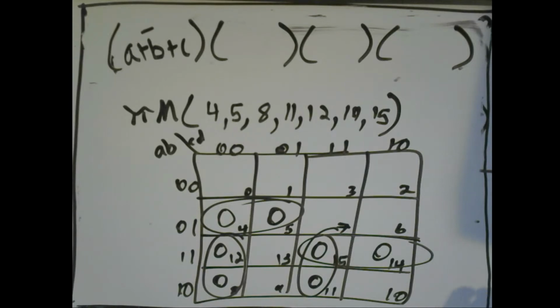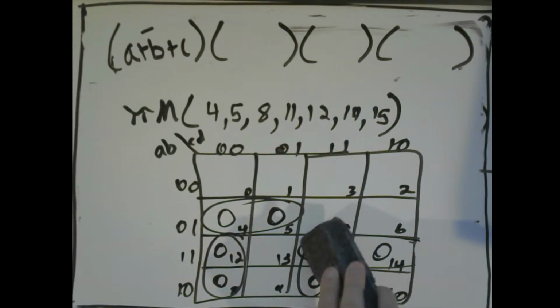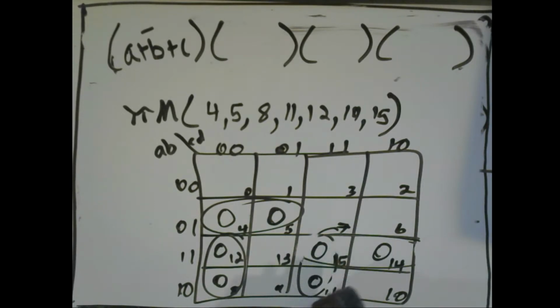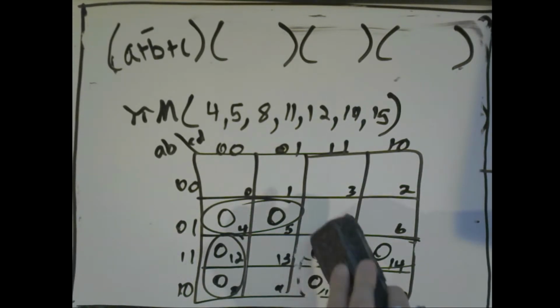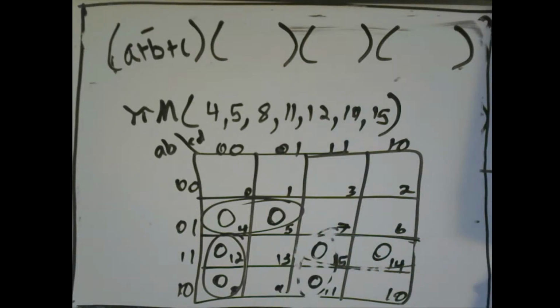And so Joshua was saying that's a good point. What would it matter if the prime implicants are different but still cover the same squares? No, there are different right answers, right? Because I'm trying to cover the most terms with the least amount of implicants, but there's multiple ways to do it.